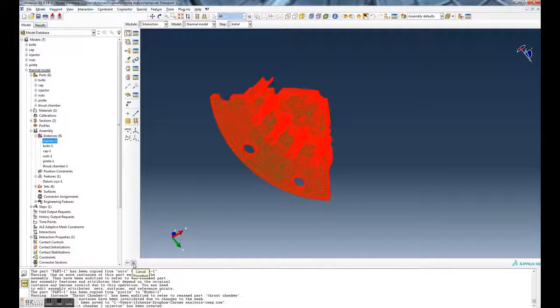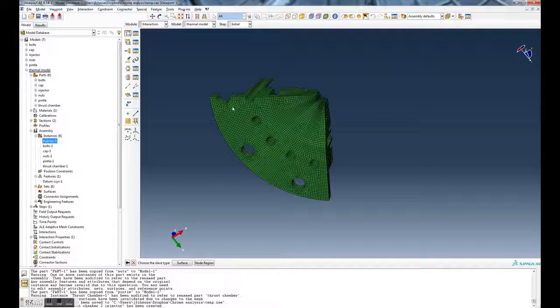So I'm going to close out this step again. This is not the defining the contact step, but this is the step of showing the elements I need to define the surface. Okay, so now you can see we're back to choosing the slave type. Pick surface. Again, by angle is fine. You know, usually I don't create a surface, but you can and give it a name. But usually I just get inundated with a lot of surfaces. But it's fine. You can do that if you want.